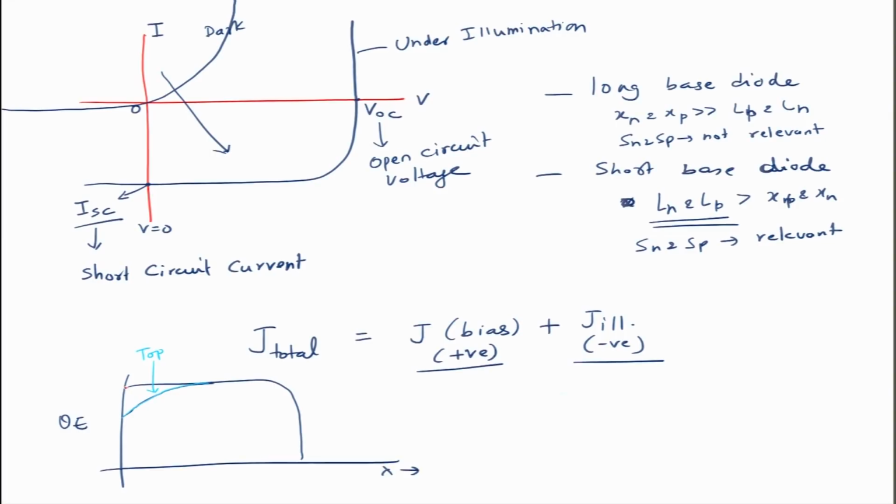and if your quantum efficiency is decreasing on the higher wavelength side, then you know that this is mainly from the bottom part of the solar cell. And if you have a decrease in the middle, it comes from somewhere in the middle where you have recombination taking place or some other effects. So, this will be helpful for you to look at your data yourself if you work on solar cells, and analyze which of the layers may be playing an important role, especially in the context of bilayer junctions like PN junctions, wherever you have silicon kind of solar cells.